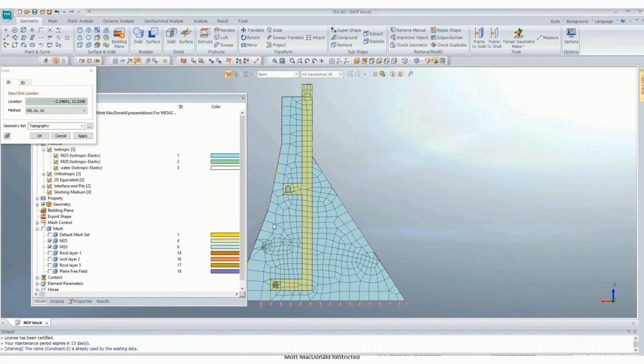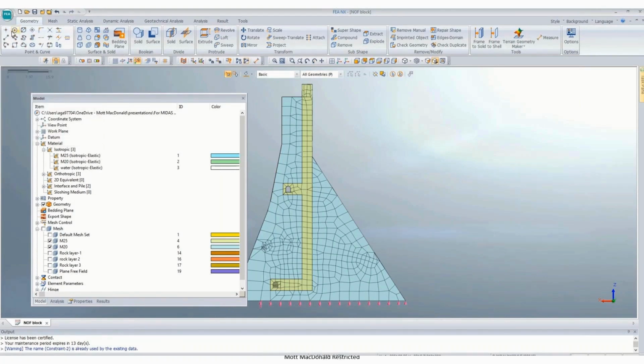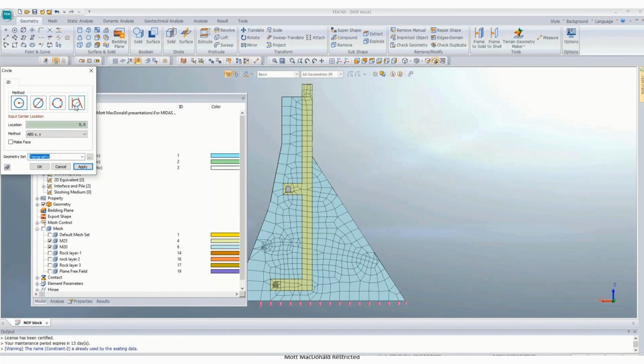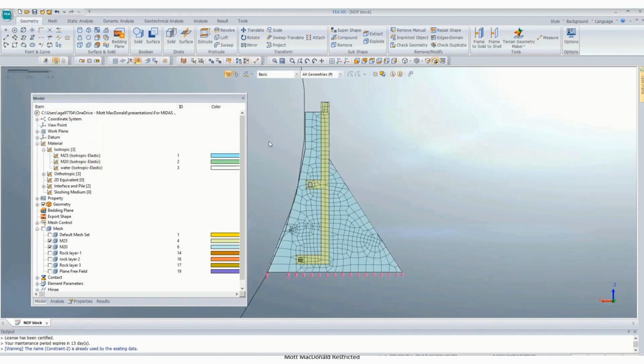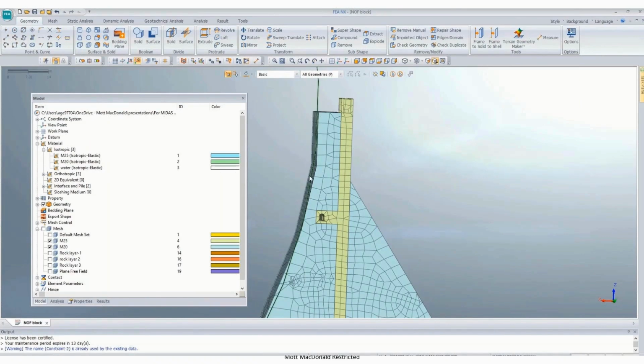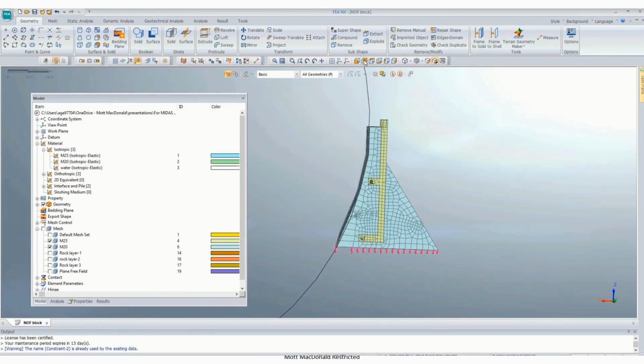I mean, this will be a curve with, say, 150, 175 radius, with this tangent and this tangent. So even this small curve will help to reduce the tensile stresses on this face.